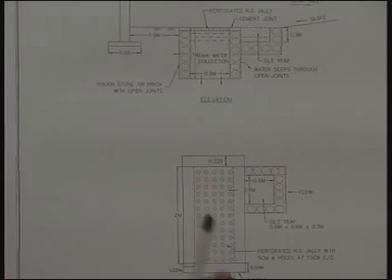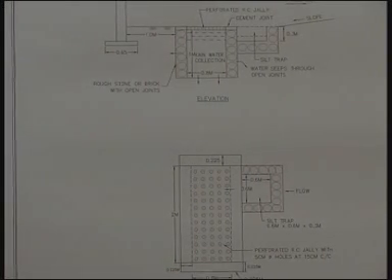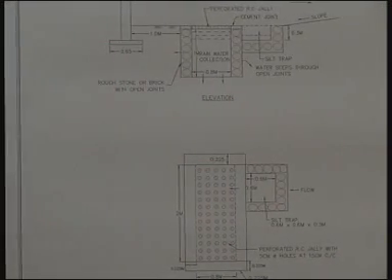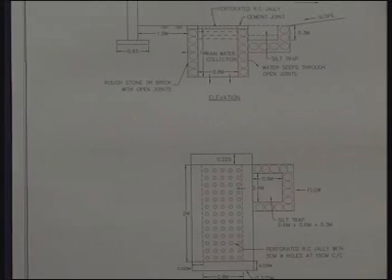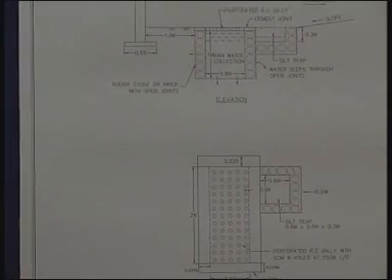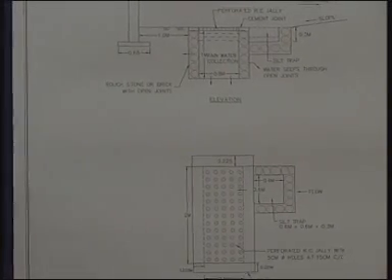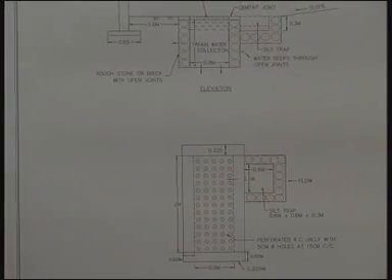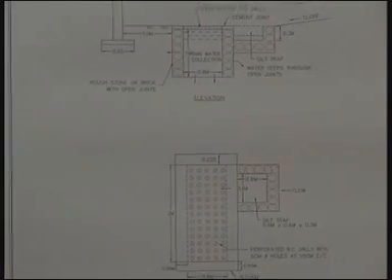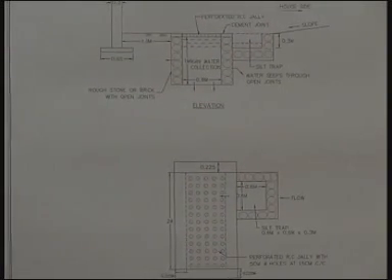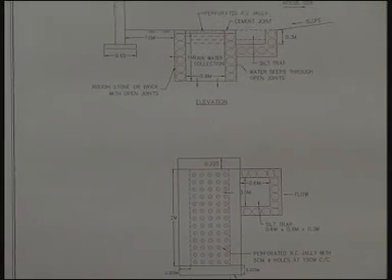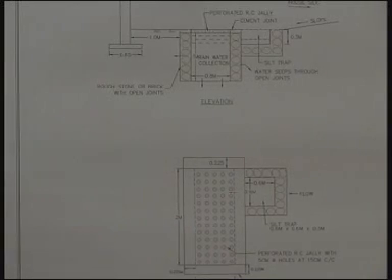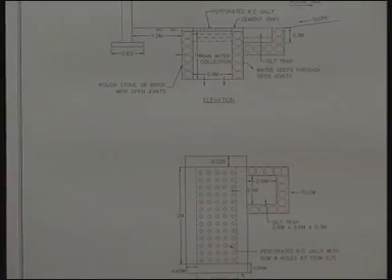For example, there will be streets and open areas, and rainfall occurring in the streets as well as in open areas like playgrounds or big office compounds or any other area of public utility. The runoff will be flowing in the streets, and such runoff also has to be collected and stored in a recharge pit of adequate size. We will now deal with that in the next sketch.